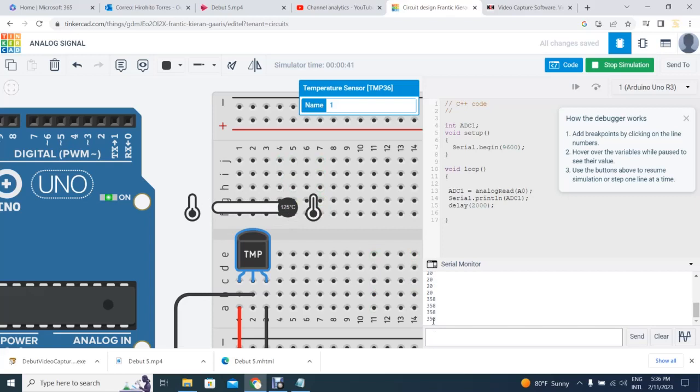So let's say if I try to do a calibration with only 2 points, I might miss the fact that it's not linear. So I need more than 2 points to ensure that yes, the calibration is as linear as it can be from the range of temperature that this TMP can measure. Like for example, from -40 to maximum temperature, which in this case will be 125.